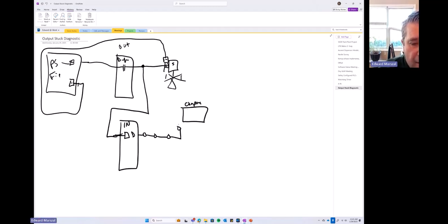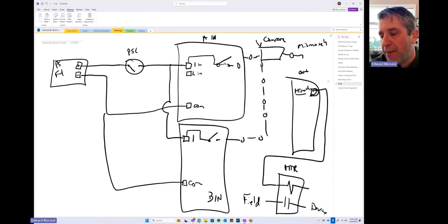where I'm going to compare the measured value, so this is the measured value going out to the field, and then there's also what the logic can tell me was the command. So if the command and the measured value don't match each other, I've got another mismatch. So I'm going to take that mismatch and I'm going to go back to this guy. I'll redraw it again on the other page, but it will be that same contact.